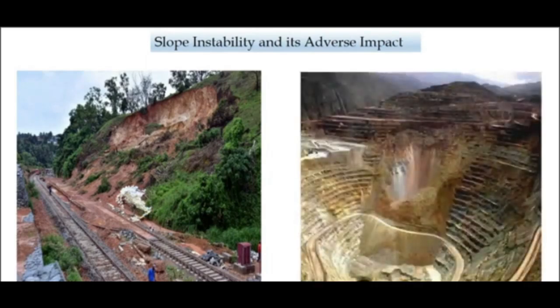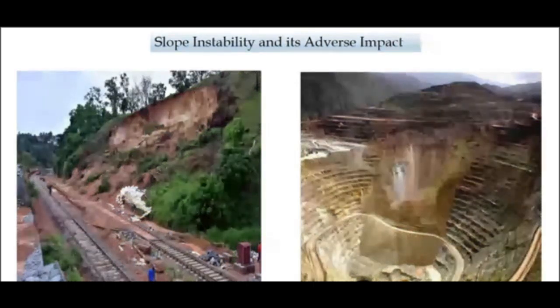Apart from the civil engineering applications in the field of roadway networks and railway networks, there is one more wide application of slope stability, which is in the mining industry. Now we know that the extraction of materials or minerals has led to excavation at deep depths, and along with the extraction, one associated issue is the dumping of the waste material. Generally, we have dump slopes, and these may range in height from 50 to 100 meters to even 500 to 600 meters.